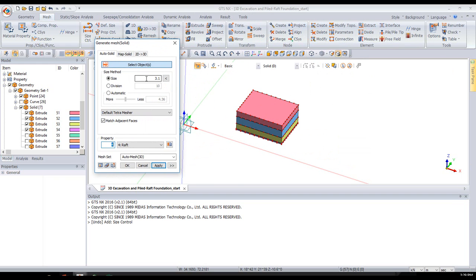And in this case, we will do by layers. I will give it a size of 1 meter, and I will use the type of element hybrid. This is a topsoil excavation, and it will have topsoil material. I'm going to call this excavation 1.